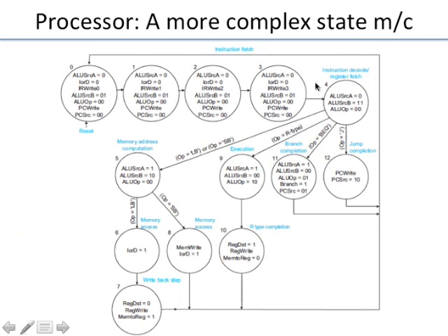And so first, in the beginning, there is some instruction fetch. It takes some 4 states to fetch the instruction in this particular microprocessor. And then when they get it, they do a decoding of the instruction out here in this state. And once they decode, they figure out what kind of instruction it is. Is it an instruction to fetch something from the memory, or to access the memory? Is it an instruction to do some arithmetic operation? Is it an instruction which is saying, should I jump? Is it a branch? Right? Or there's a jump, right? So in this microprocessor, these are the only 4 possibilities.